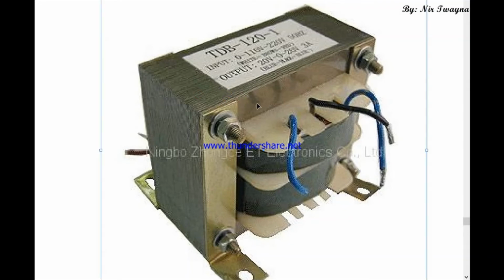So that the current produced within a stripe won't have to flow throughout the core. It will flow only within the stripe. One stripe is insulated from another stripe by using shellac or varnish, isn't it?